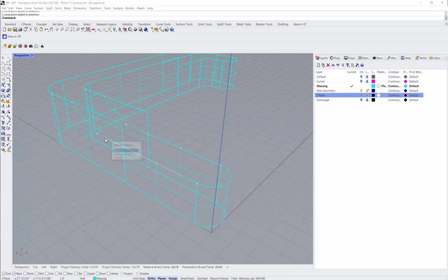We can go ahead and delete the curve that was indicating the vector between the second and the end point. And to verify the position of these points, we can use the command gcon to verify the difference in position, radius, tangency, and curvature between these two curve endpoints.